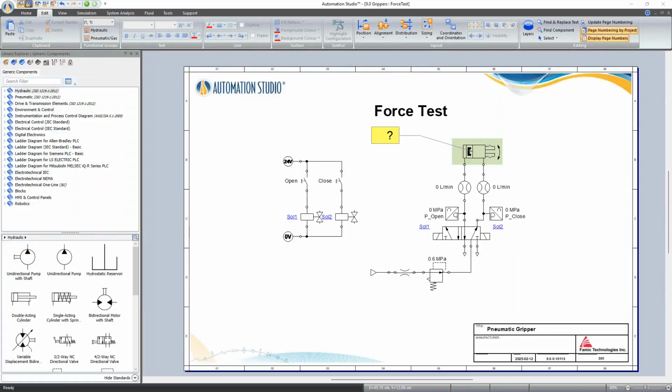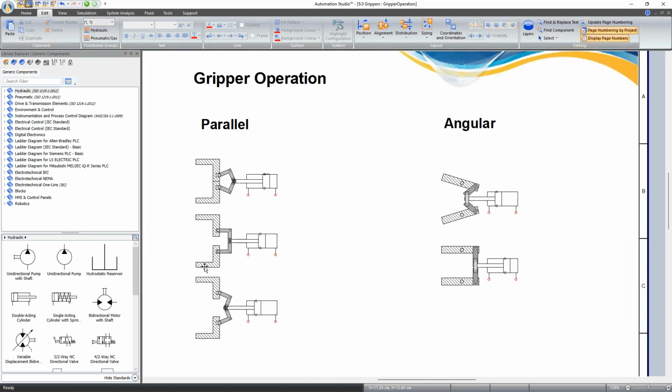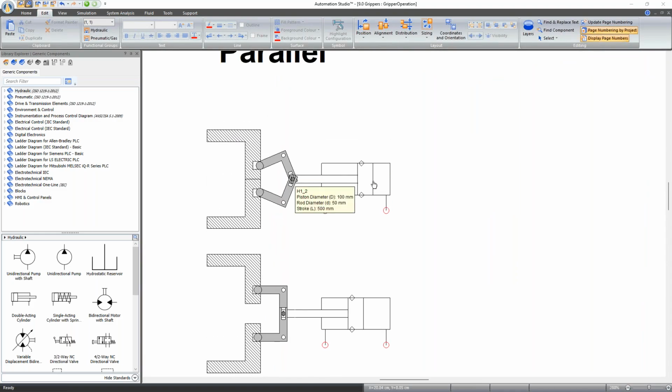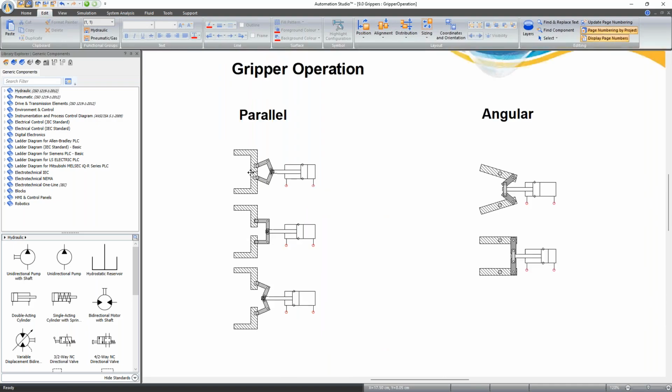Okay, just to clarify what that is, I have a little example here of how the gripper works in reality. In the background, you have some sort of a mechanism like this, whereby as the piston moves, it moves a mechanism that we don't necessarily know, but it moves linearly. Depending on the position of the piston here, the grippers will open more or less the same amount. So if the piston is at the base and it moves 1 millimeter, this will move a certain amount of millimeters based on the lever ratio.